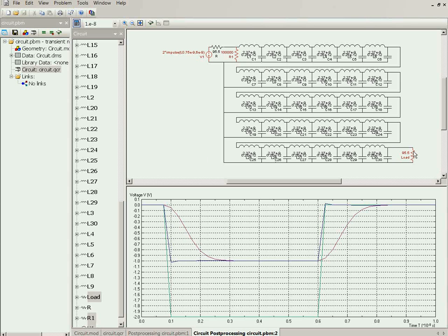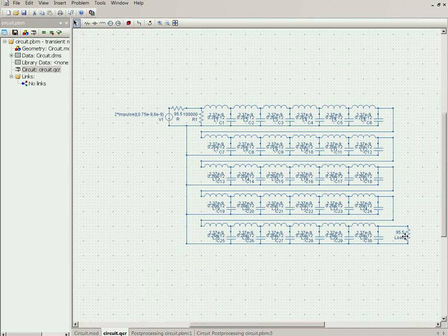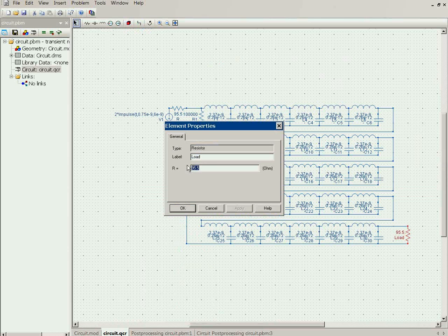If the end of the transmission line exhibits some impedance other than the characteristic impedance of the line, a portion of the signal will be terminated to ground and the remainder of the signal will be reflected back down the transmission line toward the source. The amount of the signal reflected back is determined by the reflection coefficient. With open load, the reflection is 100%.